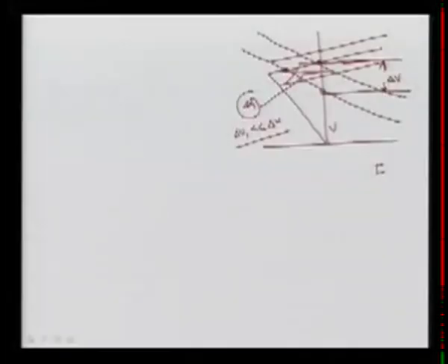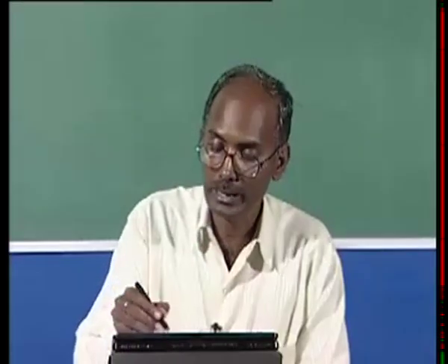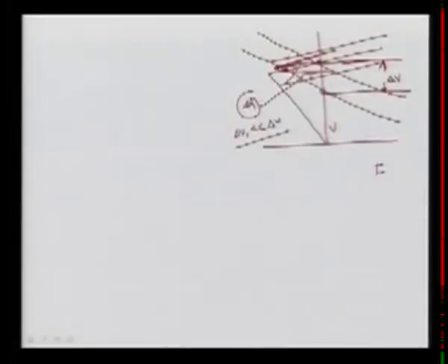At the same time, we can change these characteristics here and there by the firing angle, and even then we can maintain the voltage with this load line and get this characteristic, and the voltage can also be fixed at the terminal voltage. So whenever this load and voltage variation takes place, by changing the firing angle we can change the characteristic and maintain the terminal voltage at its rated value.